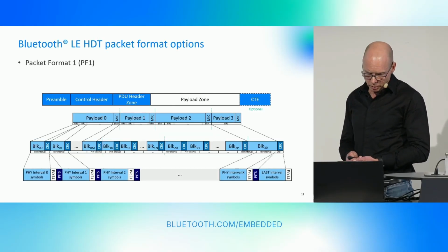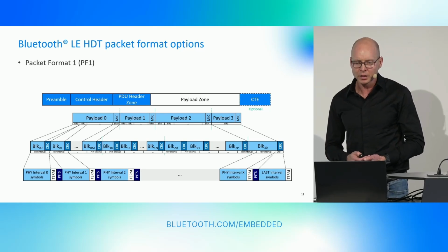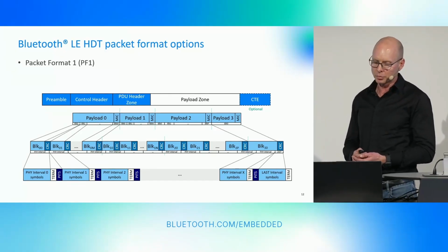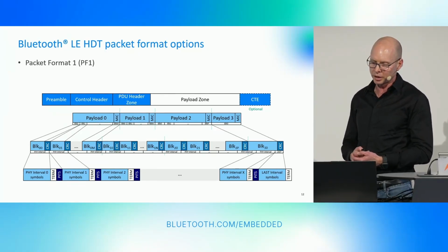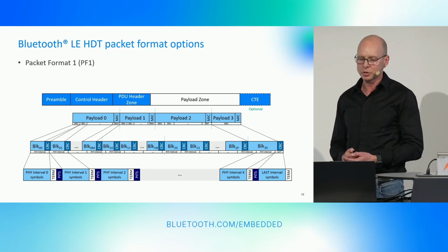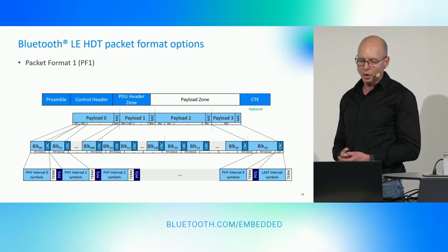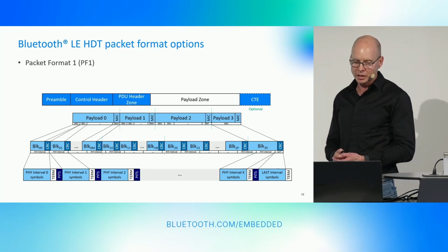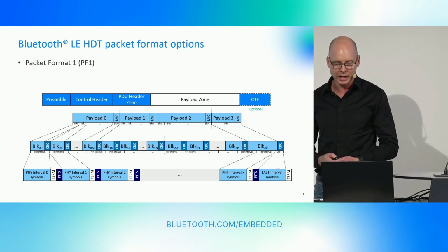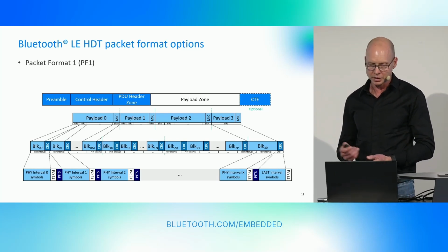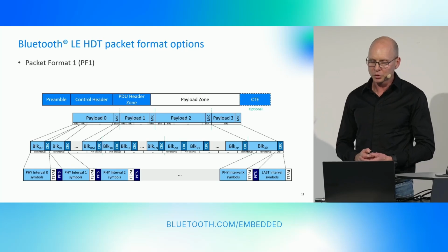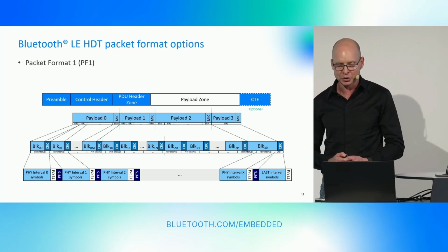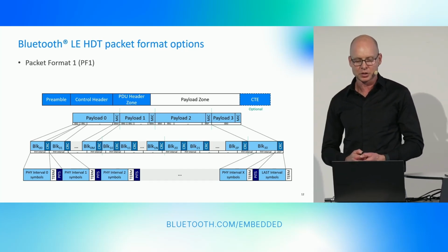Then each phi interval is followed by a terminating symbol sequence, which you see denoted as TERM. The terminating symbol sequences are followed by a phi interval training sequence, denoted as PITS on the slide, except for the last phi interval, as you can see. The phi interval training sequence is used for data-aided tracking of phase and/or channels.